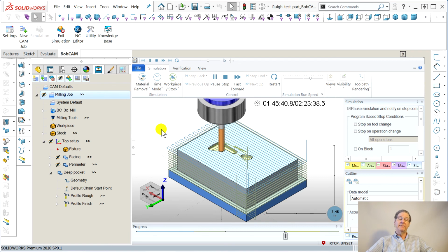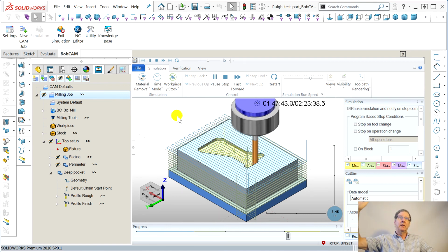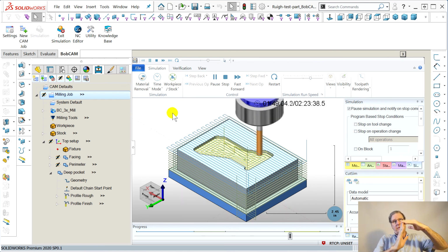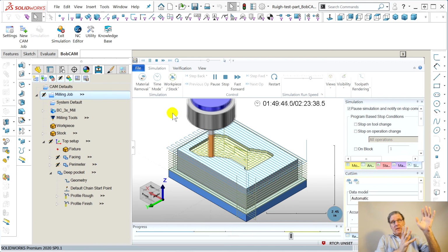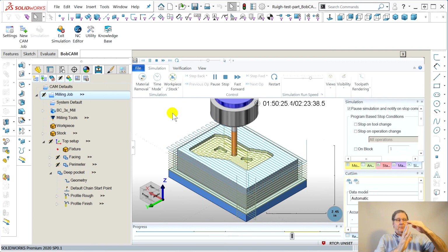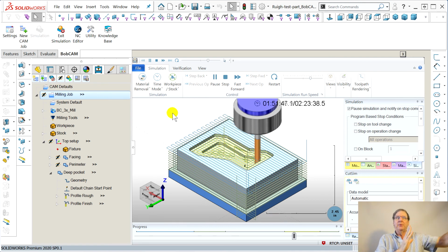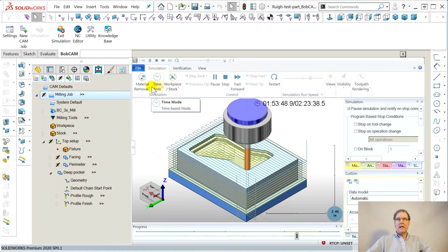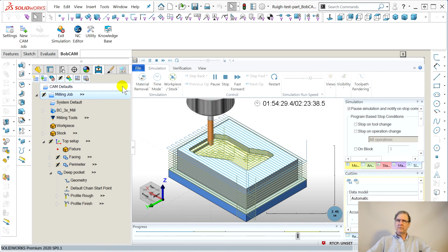See, now it's happy. It astonishes me that it would make that mistake, but then it astonished me when SolidWorks CAM plowed a tool through the side of the part. I think this all goes back to when you could have a chamfer. The chamfer wouldn't be drawn in SolidWorks because we all had 386 computers. So you'd let your CAM whack a chamfer, even though there's a model there, you cut through the model to put the chamfer on. So the programmers just have this attitude, oh, you can cut through the model. That's no big deal. I wish they'd have more of a, hey, this operation is going to carve up your part. Do you really want that?